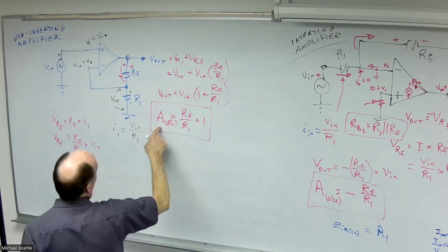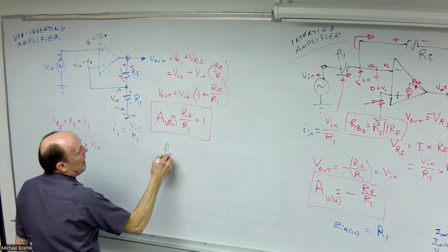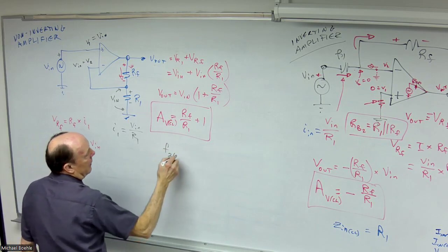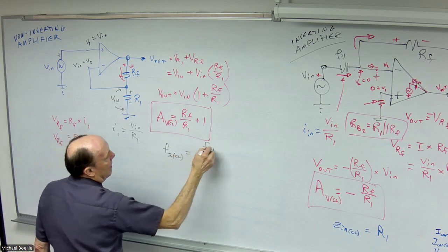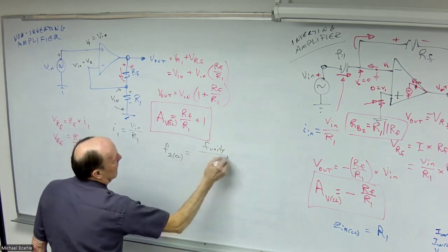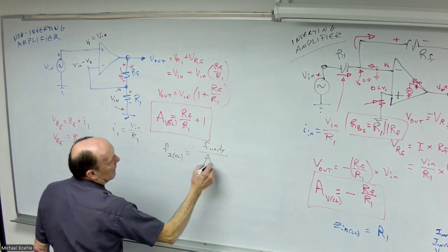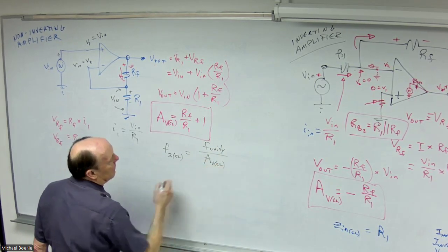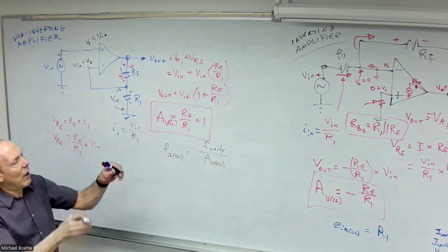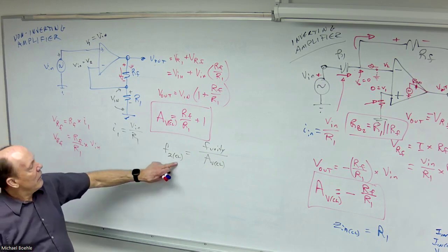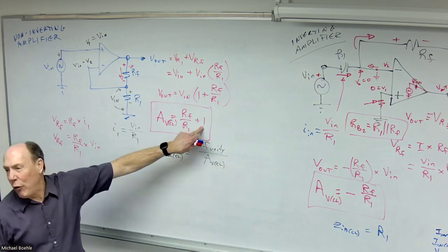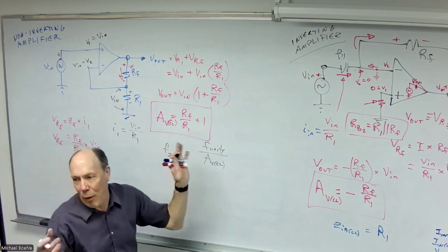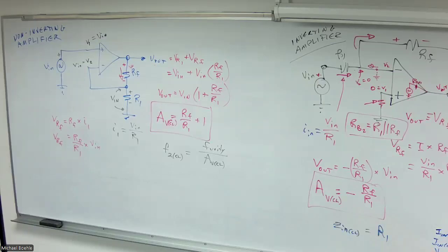By lowering the voltage gain, I increase the upper cutoff frequency. This time I don't add the 1. It's just the closed loop voltage gain. So you can kind of see where these are similar, right? So the formula for the inverting amplifier is voltage gain plus one. I've already got the plus one there as part of that formula. Where it kind of works out.